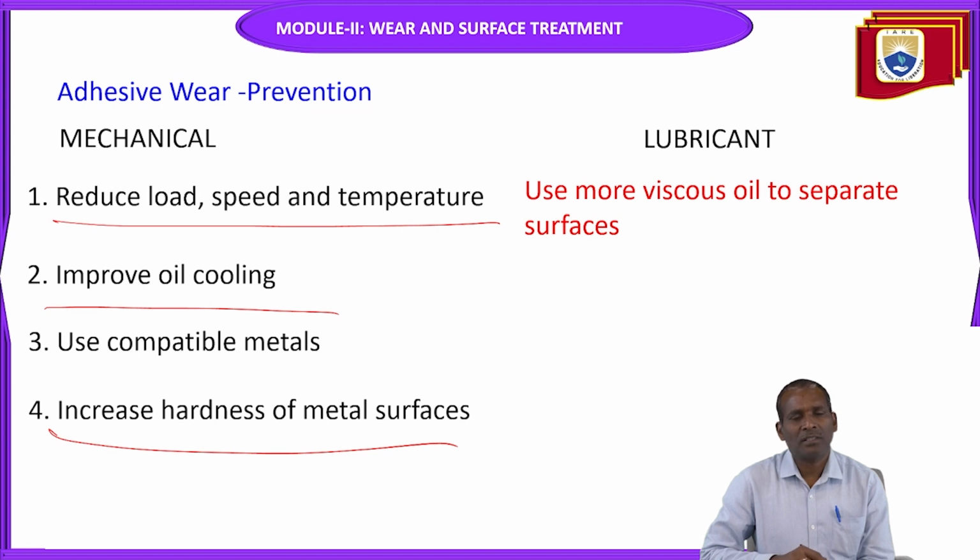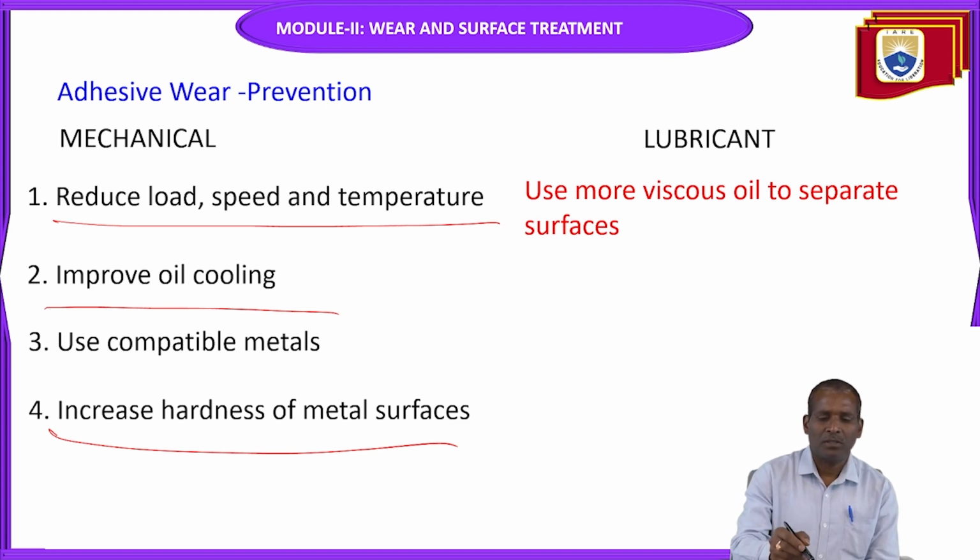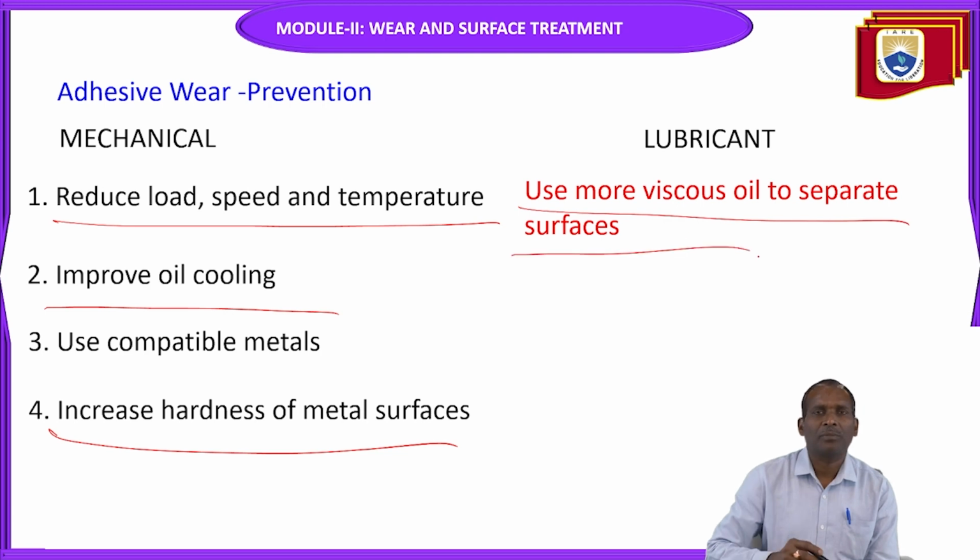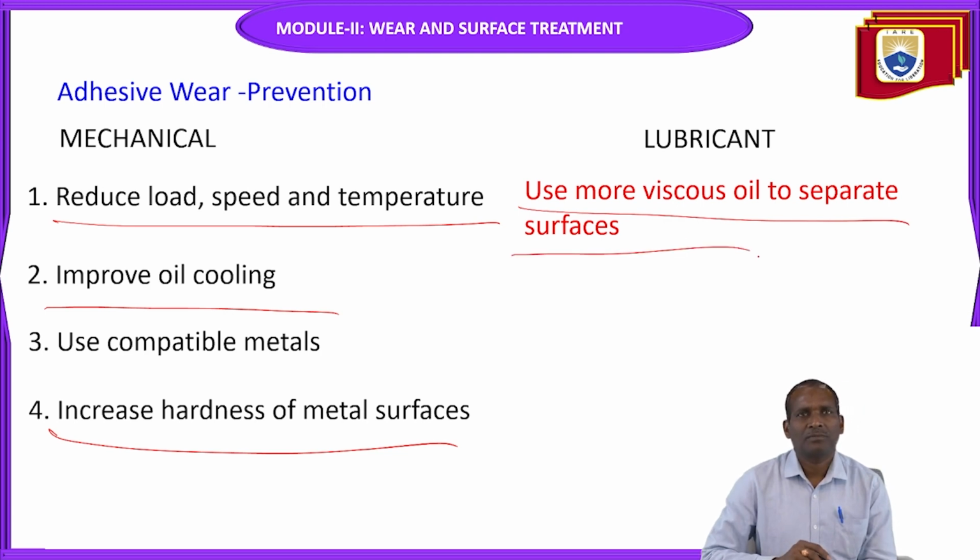So lower hardness of metal gives more wear. For this, use more viscous oil to separate surfaces. Without more pressure, smooth separation of surfaces will be possible by using viscous oils.